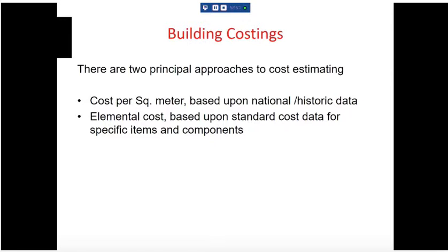yes, that sign-off business, I keep harping on about it. After RIBA stage 2, you literally get your drawings, you go and have a meeting with the client, and we literally get the client to sign on the top right-hand corner of the drawing saying, I'm happy with that design. At the end of RIBA stage 3, your pin-up stage, we literally get them to sign the drawings off. In that way, we get the client to be serious about, we're happy with your design, we realise you're now going to develop it in detail. And if they want to change their mind later, we ask them to pay us money to change the drawing. So this sign-off business is very important.